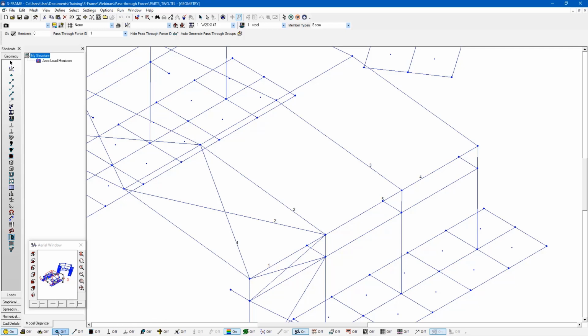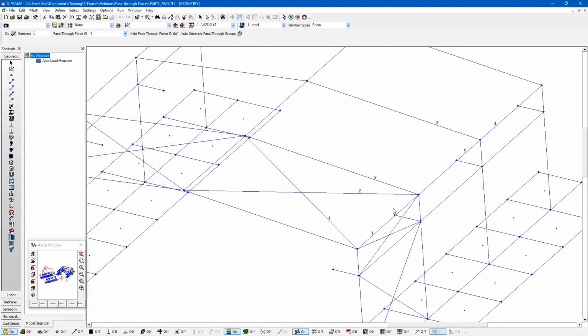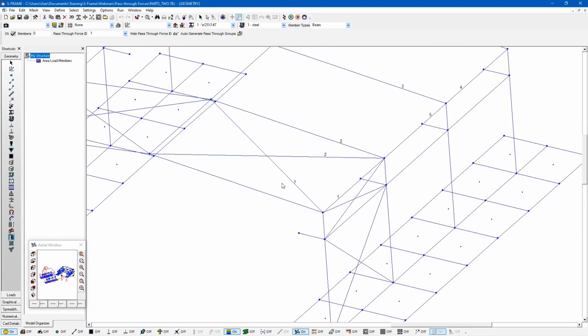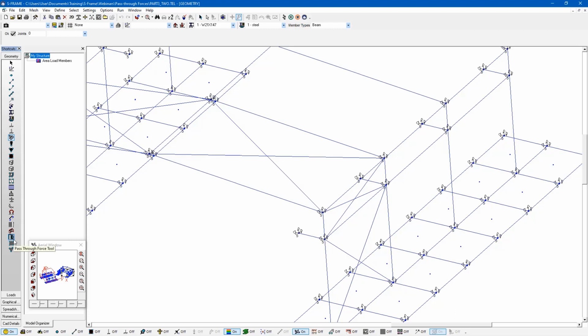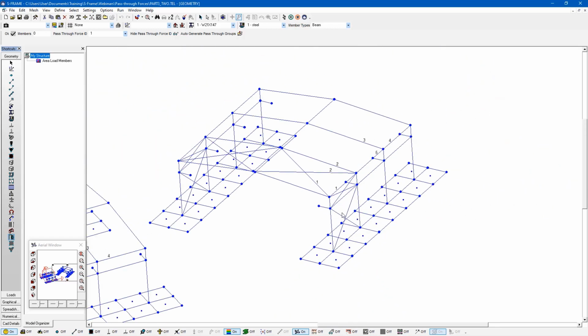Now on the other end of the model, I've also got some other things going on here. You can see that I've got basically the same model, but it's just been rotated slightly. The only change that I had to make here was I just wanted to rotate my joint coordinate system, which is very easy to do using the user coordinate system tool. I can just make sure that I have the orientation of the joint matching the orientation of my desired connection components. This way, when I look at the pass-through force IDs, which happen to be the same contributions, pass-through force ID number 1 to these two members here, that will be all with respect to that orientation of that joint. So it's not going to be doing it in the global XY because it's changed the orientation of the whole structure.